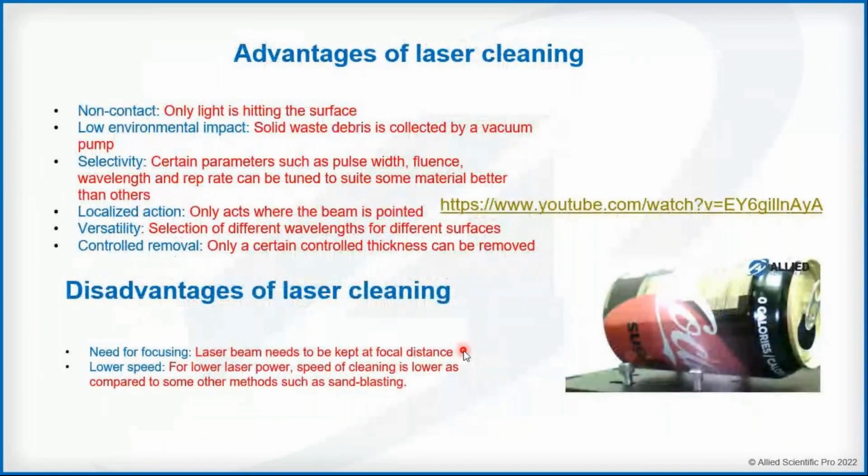Now, what about the advantages of laser cleaning? It's non-contact. There's no secondary medium, so it's only photons that are hitting the surface. Low environmental impact, because all the debris is being collected on the spot. It's a dry process. And then you have selectivity, localized action, versatility, and controlled removal.